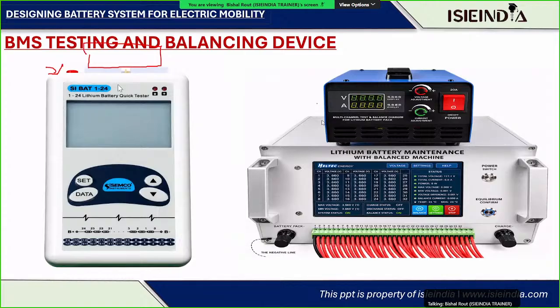But prior to connecting the battery pack, just remember, whenever we test the capacity, first we charge the cell, then we discharge the cell, and then we get the capacity of that particular cell. Once the cell is completely discharged, it has a very low voltage, like 2.8 volt, 3.2 volt. Likewise, the cell voltages are there.